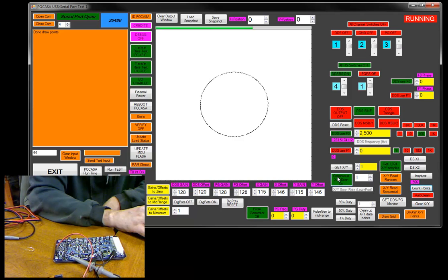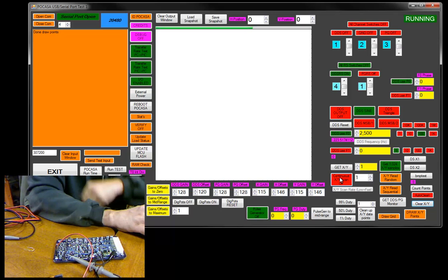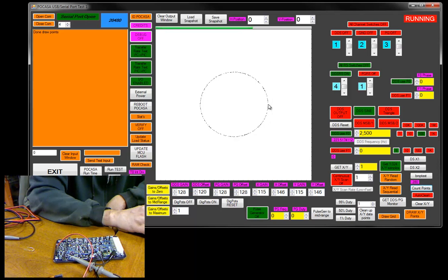Okay. Shut that off. Maybe I should time this. I'll give it 5 seconds. 1, 2, 3, 4, 5. I got 280 points, but there's a bunch of extraneous points here. So I'm going to hit auto clean, and what that's going to do is cycle through and remove any points that don't have neighbors, if you will. It's the best way I can think of it. All right, so that's gone through and wiped once. Now I got 186 points.